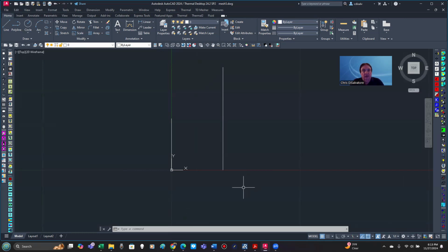If I go back and try to generate my surface, I can go back into rule surf, and select as we did before the first and second feature. And now you see we got that divided into 3 segments. So you can control the number of segments on the feature that you generate by going through those steps.